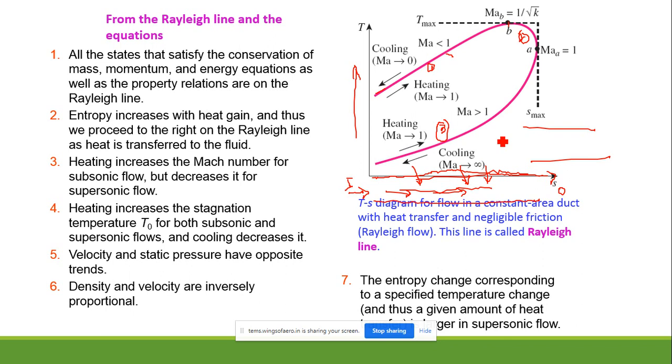Actually, see, we know for a supersonic flow, when we are cooling the gases, we can say it is like an expansion process. We have come across the expansion waves. In expansion waves, there is an isentropic process. Expansion waves come from isentropic processes only.